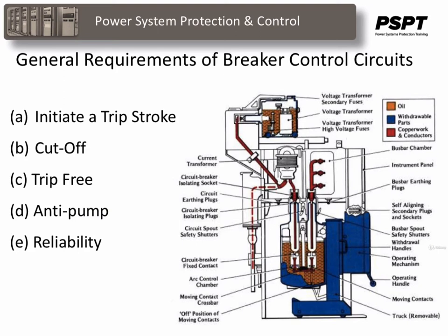This is to give extra reliability to the trip circuit. On 115 kV and above circuit breakers, there's usually dual trip buses. Thus, if a closing control circuit fuse fails during a closing stroke, the trip circuit and or circuits associated with the trip function will not be affected.